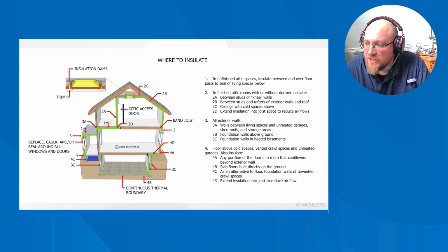You may be asked by your client, does the home I'm about to buy need more insulation? Unless the home was specifically constructed for energy efficiency, the homeowner can probably reduce the home's energy bills by adding more insulation. But air sealing is more critical. The homeowner must air seal in order to actually reduce or stop the air movement or leakage from the house.